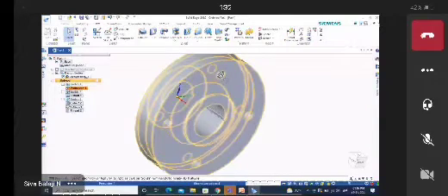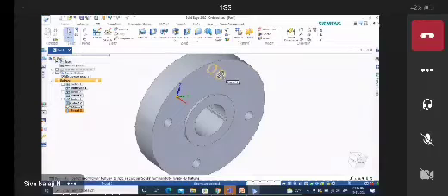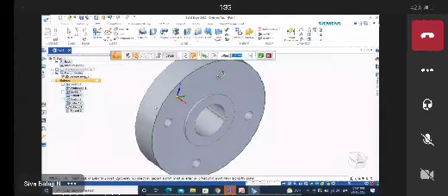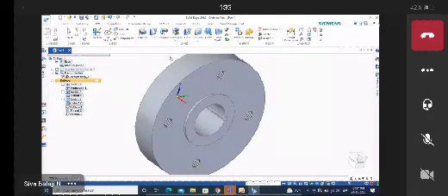Now you can select here. You have to apply it for the remaining three also. You can select the pattern command, select along curve, and select the threading. It is asking for a helical chain; you can accept that. The offset is asking, no need to give an offset. You can select next, preview, finish.